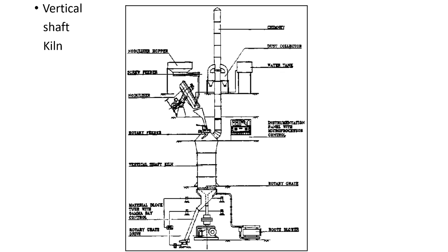The sintering is normally completed within the conical portion, which is specially designed to allow shrinking of nodules. Means slowly when the material starts burning, the nodules shrink. The various zones of reactions starting from the top of the kiln are the drying zone, the calcining zone, the sintering zone, and the cooling zone. You can see here.